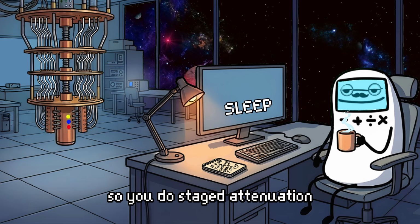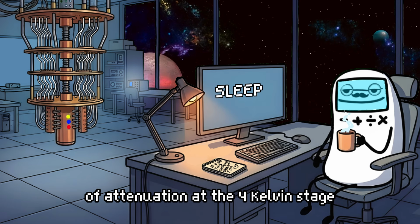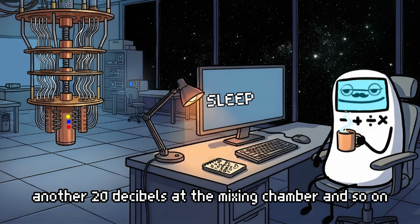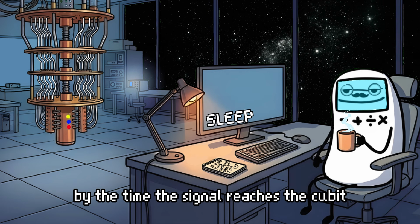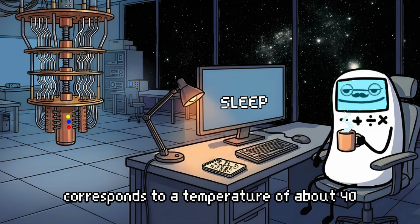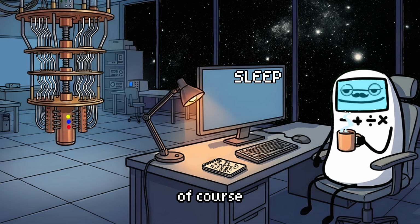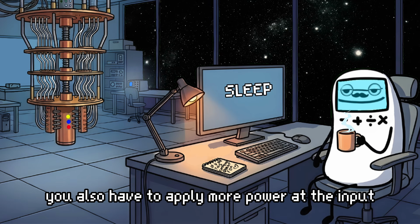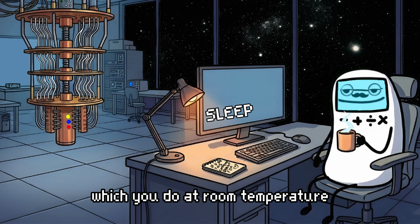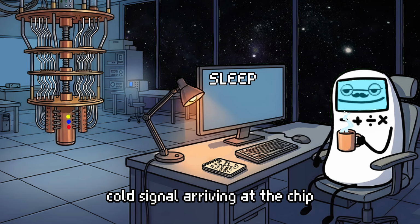So you do staged attenuation. Maybe you have 20 decibels of attenuation at the 4 Kelvin stage, another 20 decibels at the mixing chamber, and so on. By the time the signal reaches the qubit, it's been attenuated by enough that the noise floor corresponds to a temperature of about 40 millikelvin or less, which is cold enough that it doesn't disturb the qubit. Of course, you also have to apply more power at the input to compensate for the attenuation, which you do at room temperature, and the net result is a clean, cold signal arriving at the chip.